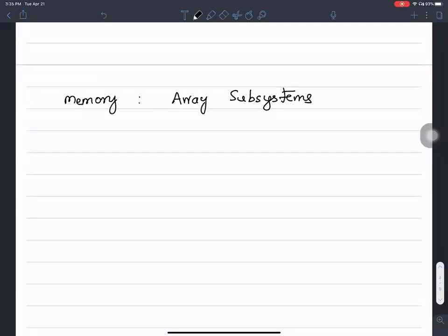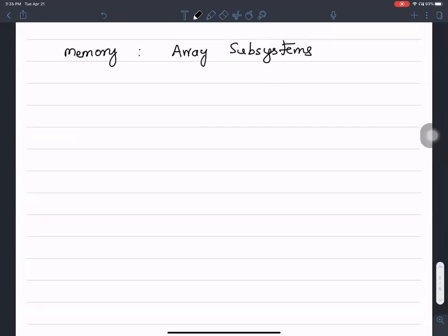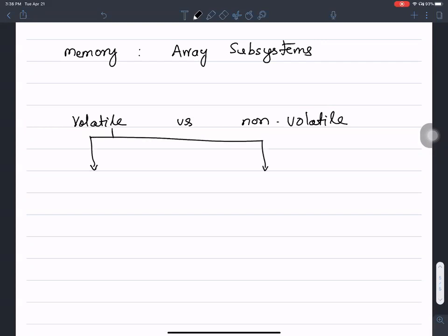Memory forms the majority of transistors in a CMOS system on chip. There are different family trees that we looked at, and then there is random access, volatile versus non-volatile memories. Even in volatile memories, there are two kinds: there is SRAM and there is DRAM, like we discussed.